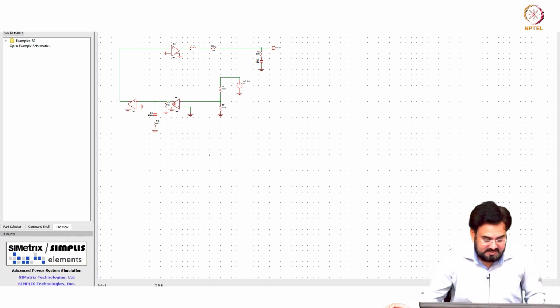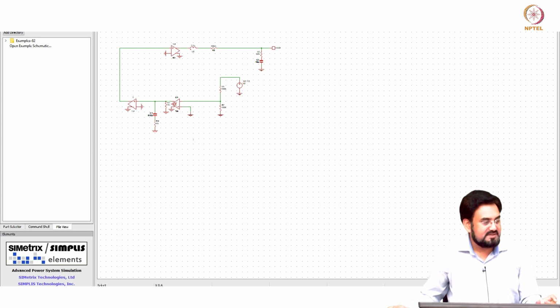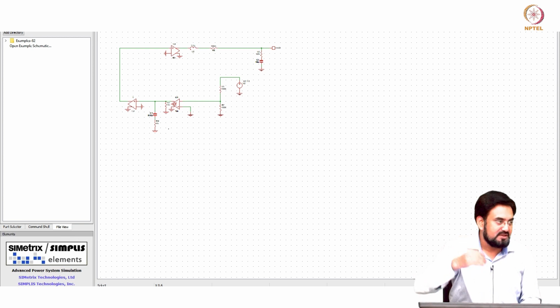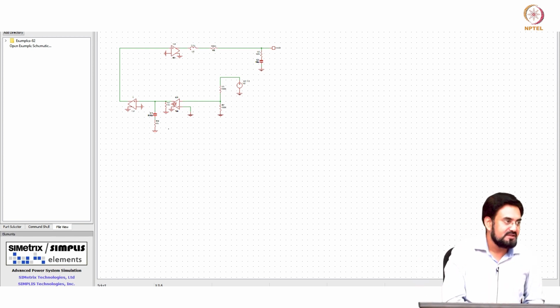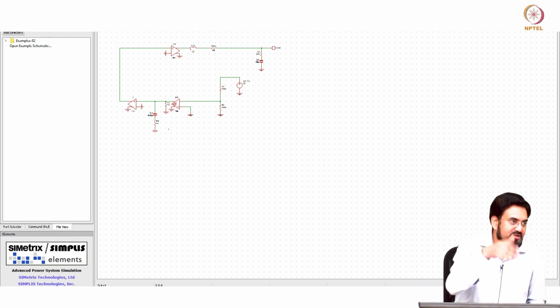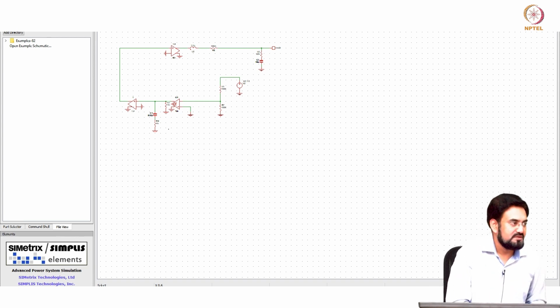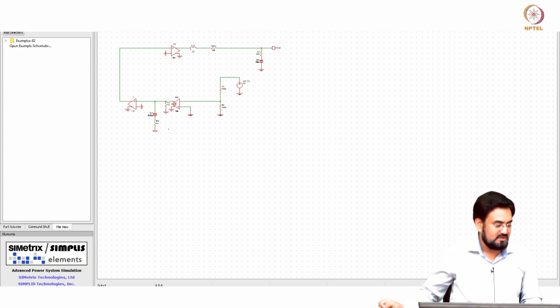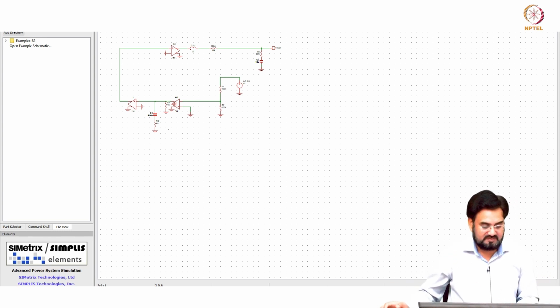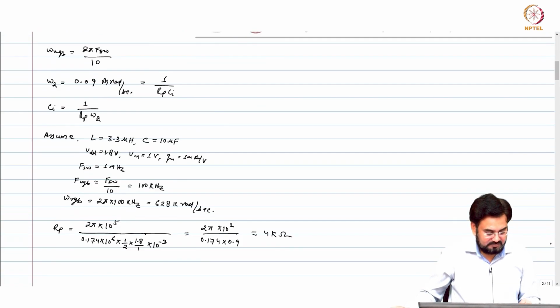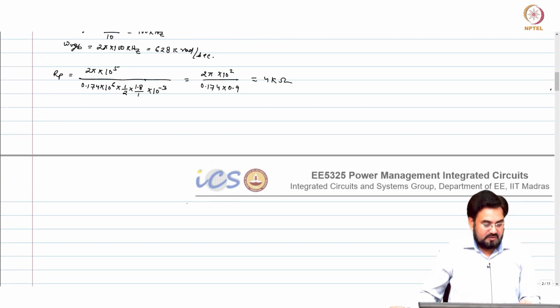So one important thing is whenever you calculate the proportional gain, and if you have a second 0, you have to consider the gain effect, because without that 0, due to resonance, your gain was falling by square, but the moment you add one more 0, that becomes first order, and that is why your proportional gain requirement changes because of that. Okay.